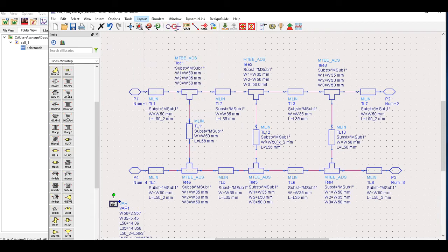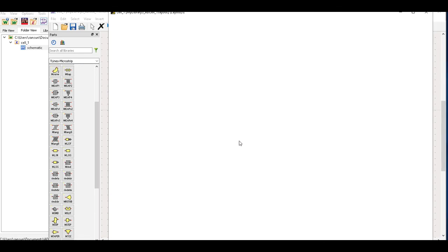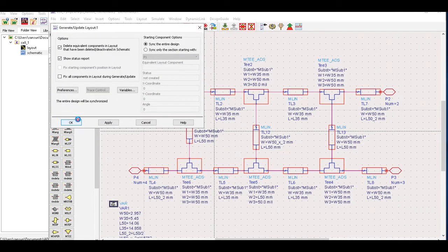Because it was not explicitly defined before, we now set our dimension as mm for the resolution. Click finish and click on OK to create a new layout, where we'll see how our design looks in the layouts, what we popularly call PCB.